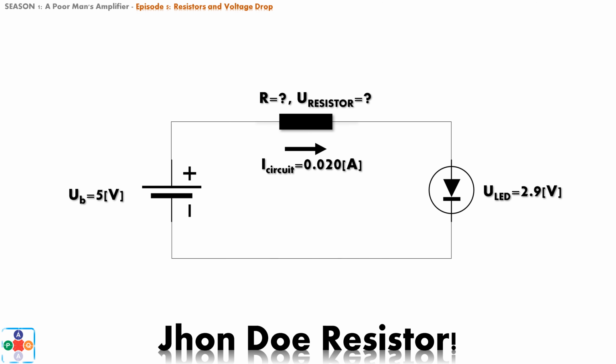We are back. So, let's plug in some numbers. From LED specifications we have learned that the optimal current for LED circuit is 20 milliamperes. So that is first parameter set. Now, for our power source, we know that we need at least 2.9 volts or higher, but batteries or other types of power sources usually don't come in that value.